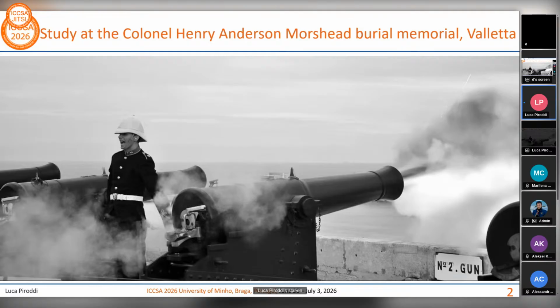The main goal of the investigation is to digitally reconstruct the internal part of the memorial as well as the external monument. The derived 3D digital model was used to identify and locate cracks that need to be looked out for, and also the large area of the monumental square was surveyed by means of a ground penetrating radar to map the subsoil.